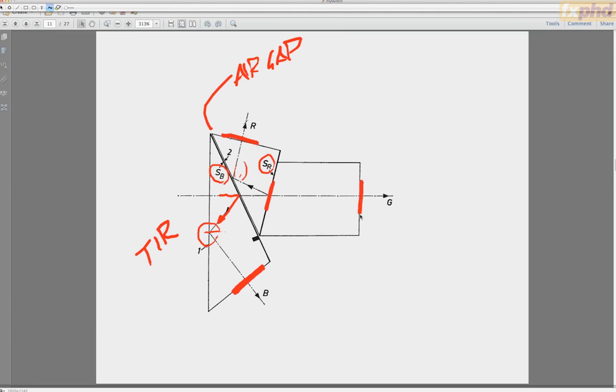The green sensor is cemented way back here. Why is it so far back? Well, because the optical path length to get to each of the three sensors has got to be identical. The path length to get to blue has got to have all of that distance inside that prism. And the path length to get to red has got to include this traverse through the blue prism, this and this, and this traverse through the red prism. This has got to add up to the same amount.